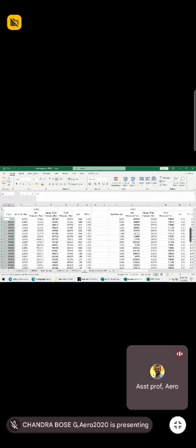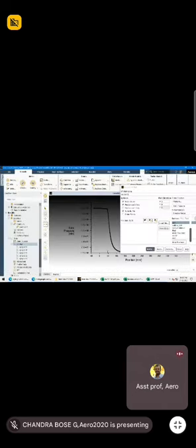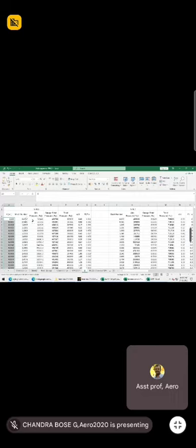Next one, I need the total pressure. Okay, total pressure is in gauge. So this is gauge total pressure. You can see Control C, just copying and pasting. You can paste here. It is gauge total pressure. It is not total pressure, it is gauge total pressure. Okay, and if you add 101,325, it will become absolute total pressure.